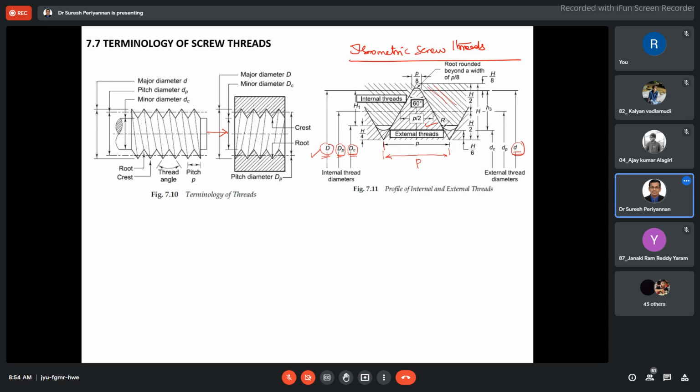Okay. Now see here. Now, if you make any bolt or nut with a sharp corner, what will happen? The stress concentration will be more. When you are preparing the threads, the roots and crests should be either flattened or rounded. When we are considering the external thread, we say crest; when we are considering the internal thread, we say roots, right?